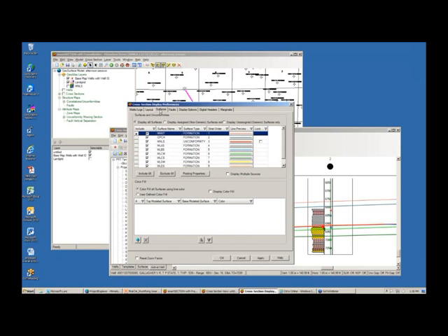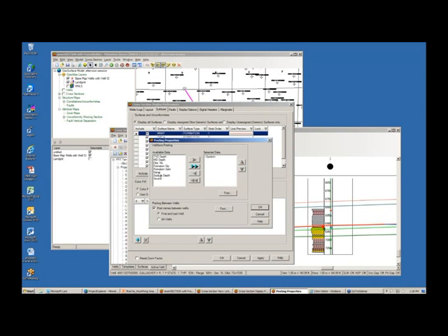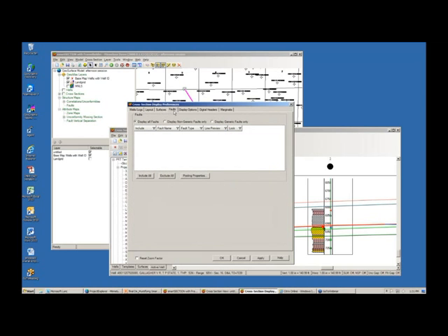The Surfaces tab is very similar to the other Surfaces tab. The only difference is that you can actually choose to put posting properties. For example, you could choose to post the name of each surface between wells, before and last wells. You can change the fonts, the colors, everything you need to do to make those surfaces look good. The Faults tab is where you would choose which faults you wish to see in your cross-section.